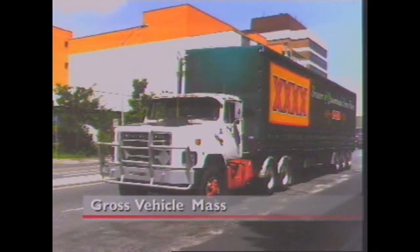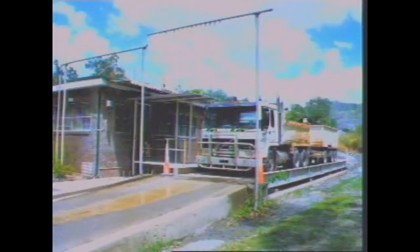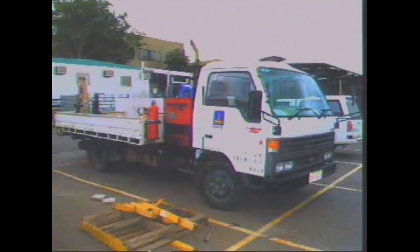Gross vehicle mass of a goods-carrying commercial vehicle is the sum of its tare mass and the mass of goods the vehicle can safely carry in accordance with its design specifications. Tare mass is determined by weighing the unladen vehicle on suitable vehicle scales. It is a legal requirement that this value, together with gross vehicle mass, be registered on the vehicle chassis frame.